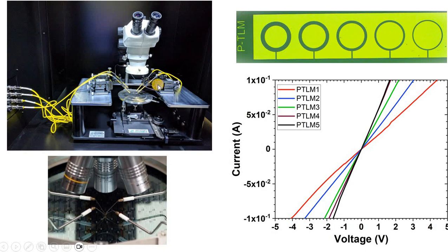You might like to use a probing station equipped with micro probes to make the electrical contacts with the metal pads. For higher accuracy, use a 4-point probe configuration to eliminate the effects of lead and contact resistance in the measurements.